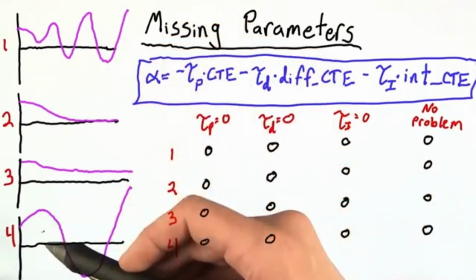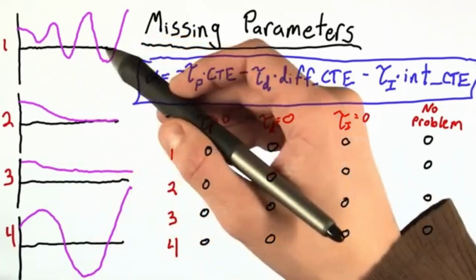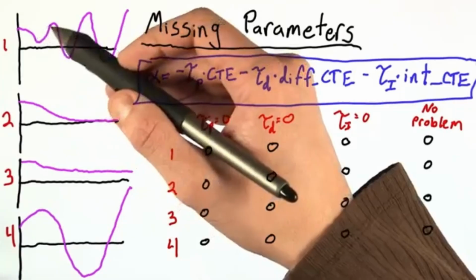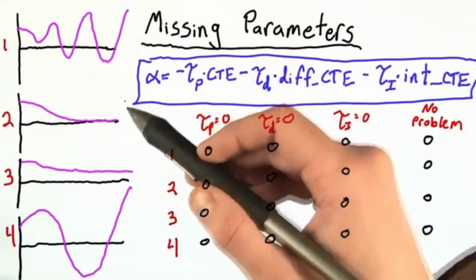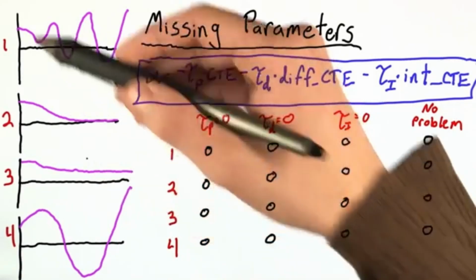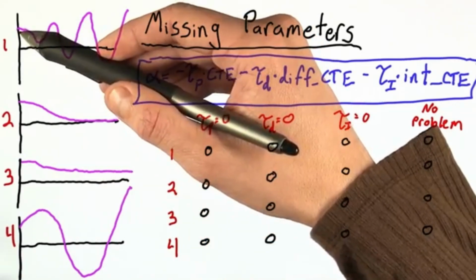In each of these four cases on the left, the black horizontal line is the intended track for the robot, while the pink represents its actual motion. In each of these cases, the robot has a 10-degree positive drift and starts with a cross-track error of 1.